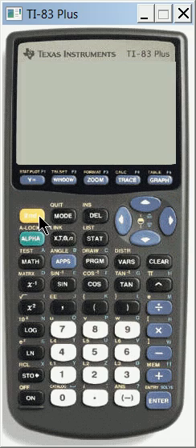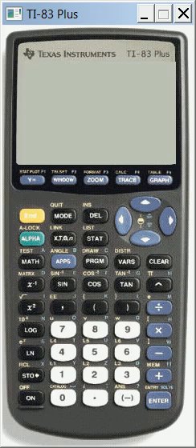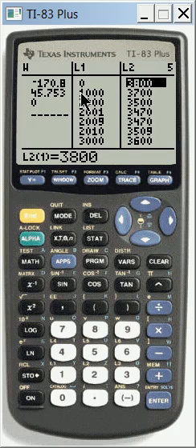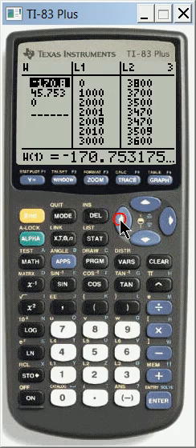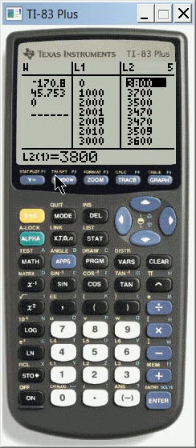All right, so that was this calculator punch. I'm going to go ahead and show you what I said you need to do with this. I'm going to turn this back on, hit y equals. I'm going to hit pause right here for 1 second. Okay, I hit pause, and what I did there is I pre-populated L1 and L2 using just my list commands. If you remember, you can go to stat and then edit, and there I've got L1 and L2. Of course, I made the mistake of populating first LU, but then I can just use my store variable to transfer from LU to L1. So you've got basically your station elevation.